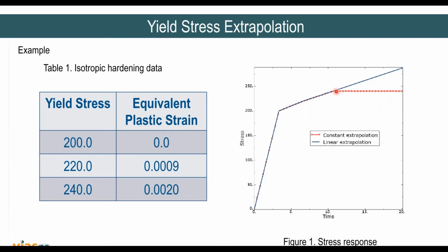So what we have provided is that it can be extrapolated linearly. Sometimes this will provide some stiffness, and it will help you run your analysis without non-convergence. Of course, care should be taken that the plasticity is localized, not at the bulk level here.